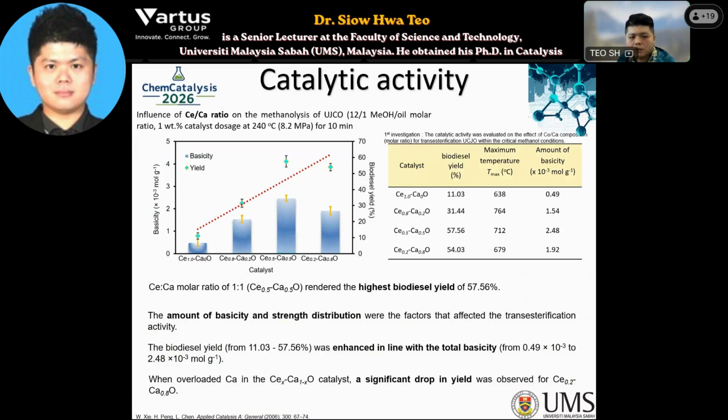However, as we can see here, when the calcium content was further increased, a decline in biodiesel yield was observed. Despite the presence of strong basic sites, this may be attributed to the excessive calcium loading, which may negatively affect the catalyst properties and accessibility of active sites.